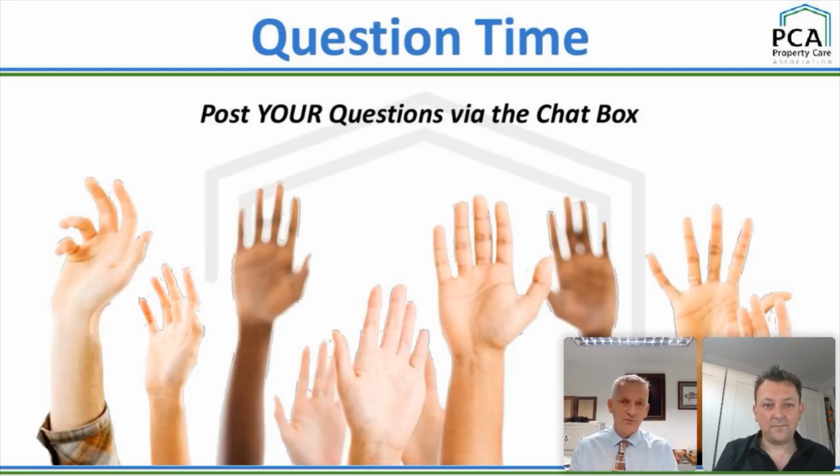Sometimes just bed joint reinforcement and monitoring, you might say to the client, well, actually, this isn't that severe. It just looks bad because it's been happening for decades. So we're going to stiffen that area. We're going to give it a bit of tensile support. And then I can't guarantee you won't get any more cracking elsewhere. You won't get cracking where we've done the work, but I can't guarantee you won't get any cracking elsewhere. But let's just monitor it, and you might find you don't have to put more movement joints in. And that's a reasonable opinion to have.